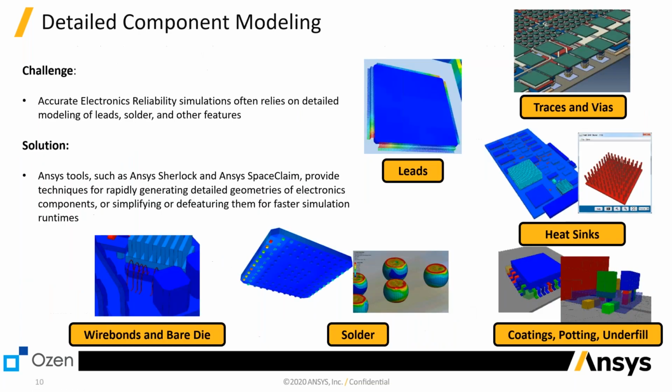So that's why this trace modeling approach is in the lower right-hand portion. It's highly accurate, but the speed is going to come down. But ANSYS provides all of these options to you. And then when it comes to detailed component modeling, as you can see here, we can take into account the wire bonds. We can take into account the solder, meaning that we can put a lot of nodes, a lot of elements in every single solder joint.